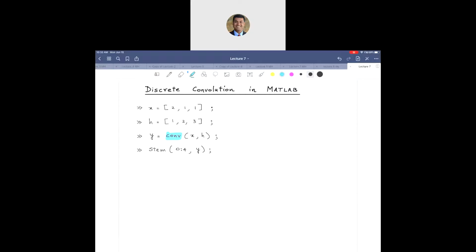This is being done in the command prompt here, so you could write a MATLAB script and fill in these MATLAB commands, or you can directly type them into the command line. If you have a few statements to write, for example, over here you just have 4, you could directly enter them into the command line, which is indicated by the 2 greater than signs here.